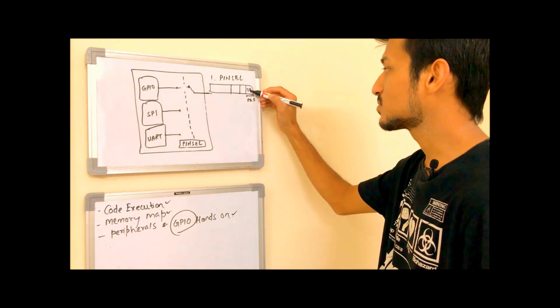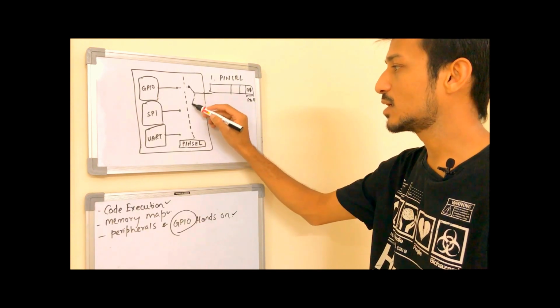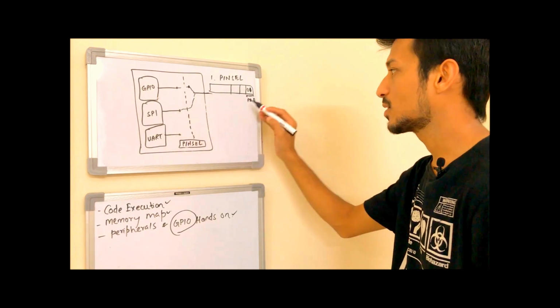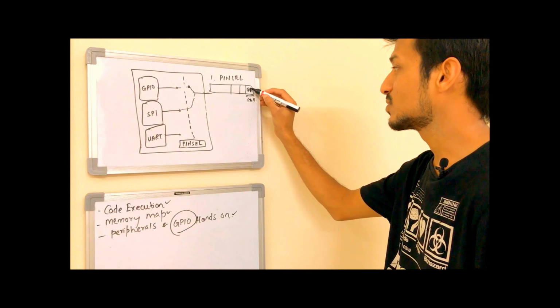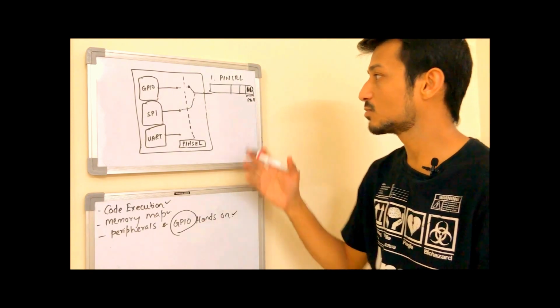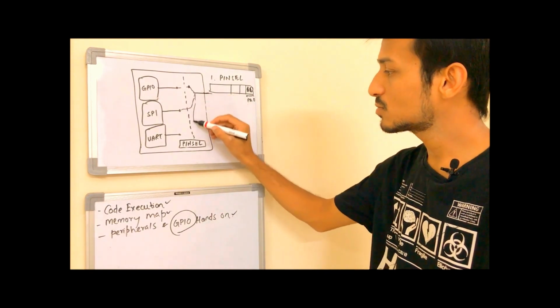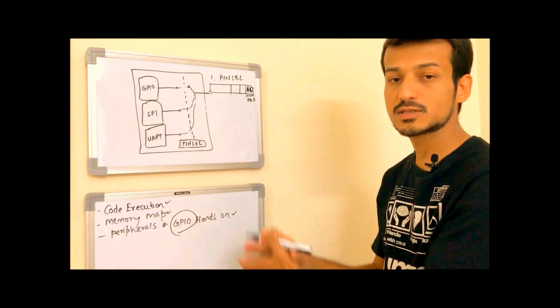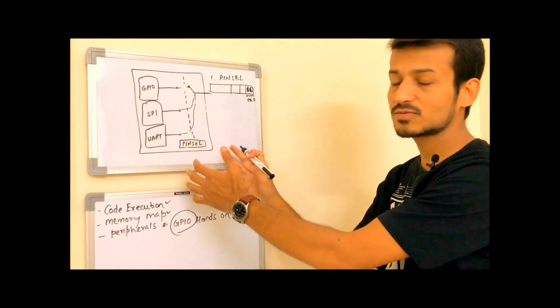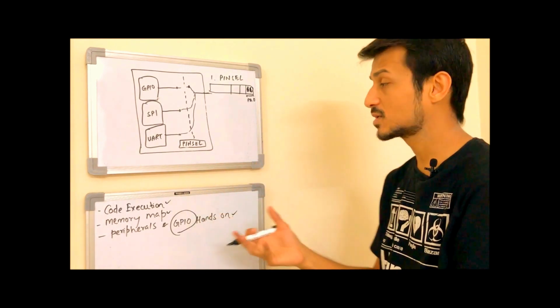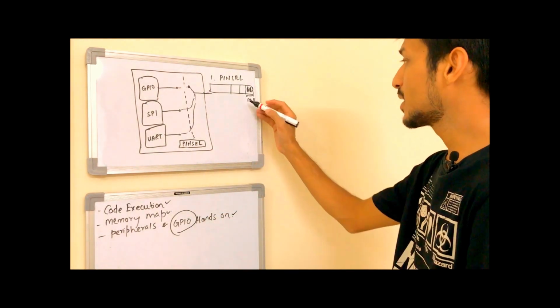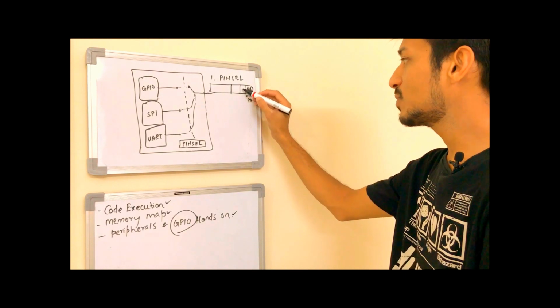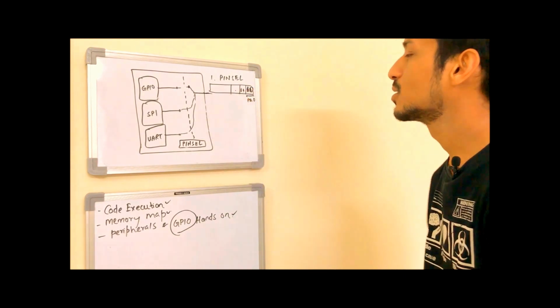If you select 1, it will be the first functionality and it will be connected to the SPI. But if you select 1 0, the value being 2, this will be connected to the UART pin. So that's how the selection logic works as a multiplexer. This is nothing but a multiplexer selection line, and each pin will have 2 bits here.